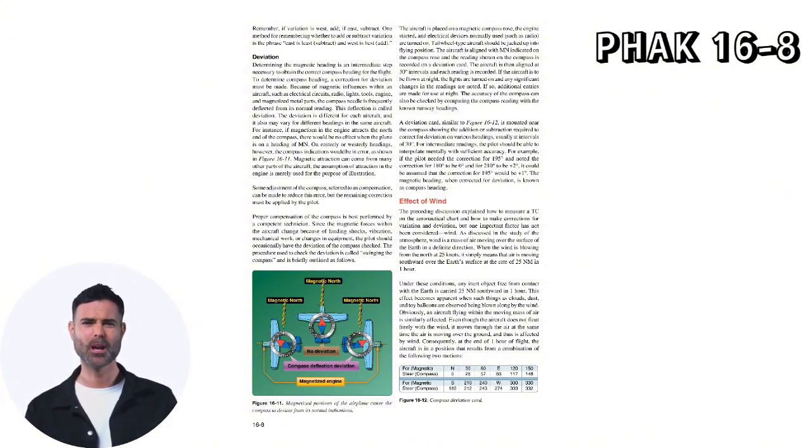Some adjustment of the compass, referred to as compensation, can be made to reduce this error, but the remaining correction must be applied by the pilot. Proper compensation of the compass is best performed by a competent technician. Since the magnetic forces within the aircraft change because of landing shocks, vibration, mechanical work, or changes in equipment, the pilot should occasionally have the deviation of the compass checked.